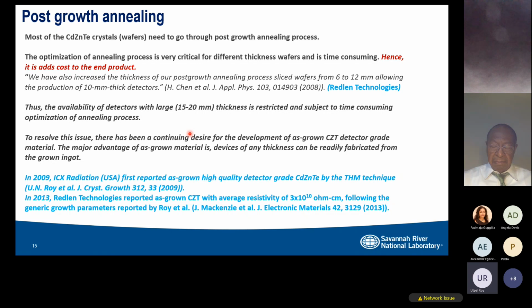And what does that do? That eventually gives a lot of thermal stress, and eventually it cracks the glass. But if you put the same volume of diamond inside boiling water, the diamond will not crack. Why? Because the thermal conductivity of diamond is very high. So immediately the temperature will be uniform all through the diamond, so there will be no temperature gradient inside the material. So the material will not crack, or it will not generate any defects because of thermal stress.